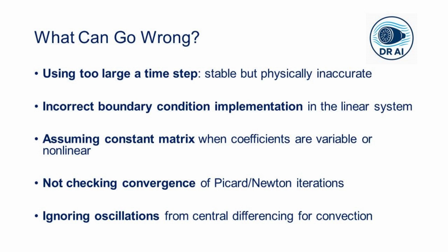The first pitfall is using the time step so large that the solution becomes stable but physically meaningless. For example, smearing out a shock or failing to capture a rapidly varying boundary condition. Always check that your time step is appropriate for the physical time scales of your problem.